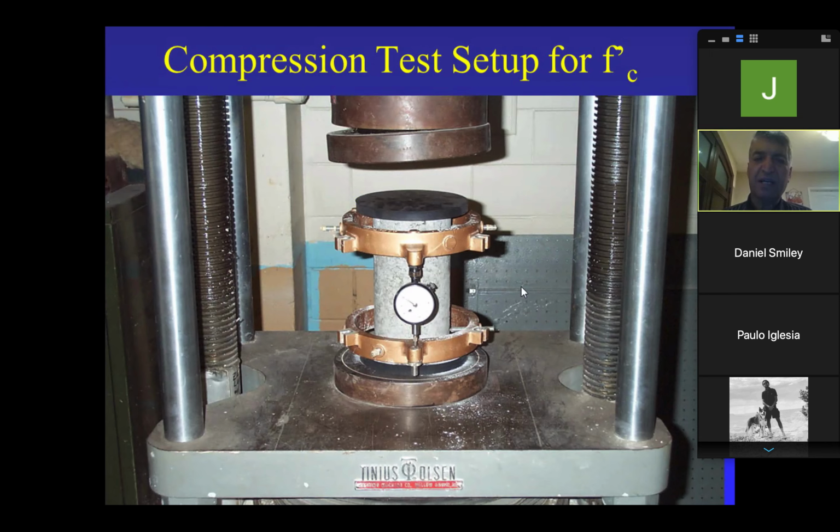So the force is coming from the machine, and the area of the cylinder. That's the F prime C. So at what force this is going to break, you take that force divided by the area, that's your F prime C. And if you are calling for 4,000 PSI, you better get 4,000 and more. But most of the time, if you ask for 4,000, the designers are going to give you 4,200, 4,300, because nobody wants to take a chance.